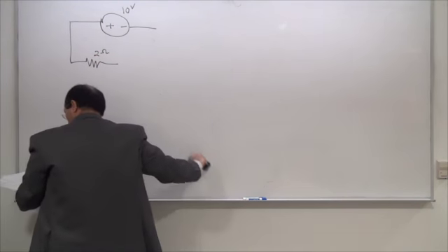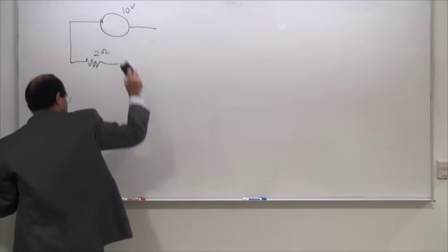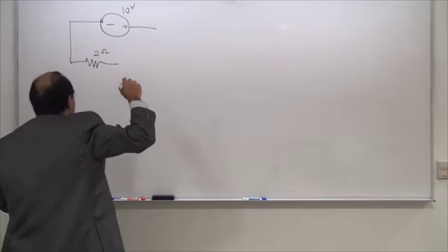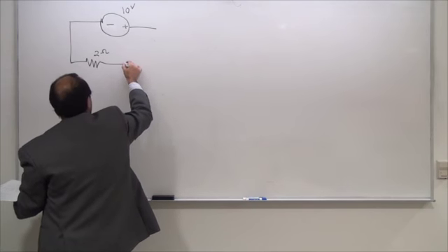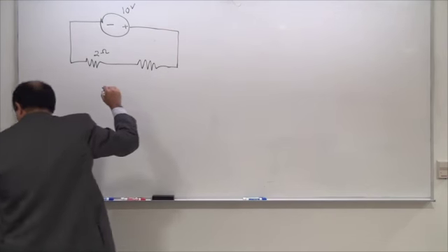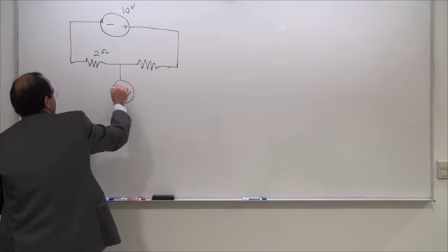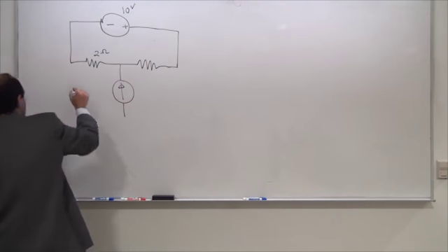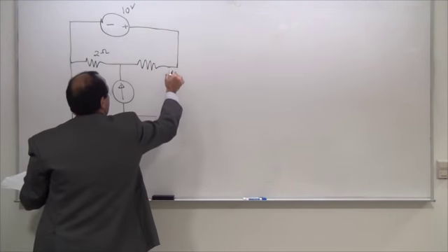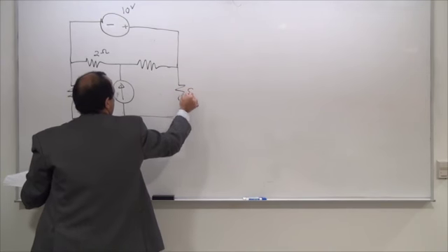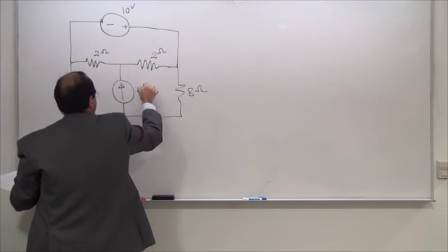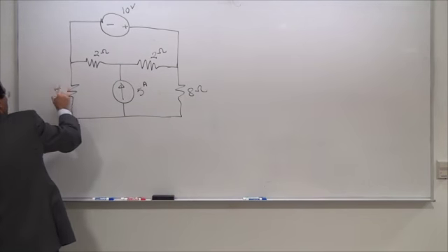Just to follow what the book says, I need to make sure the polarity is the same, so this is plus, minus. This is question 3.18, but I'm trying to attack this circuit from two different mindsets. The first mindset is that I can simply write the nodal equation. So that's 8 ohm, 2 ohm, 5 amp, and 4 amp.